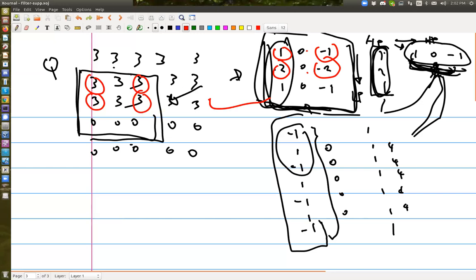But the point I want to make is that this filter is really doing a low pass in this direction and high pass in this direction, right? For this signal here, along this direction, it's only low pass, because each of the rows here is constant. Along the horizontal direction it's getting blocked. So you don't have any signal that can pass through, therefore you will get all zeros.